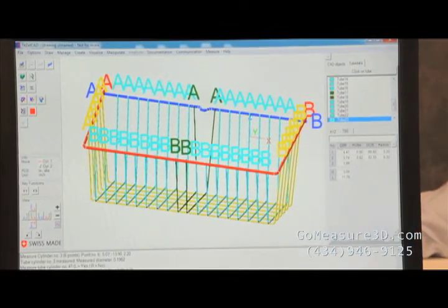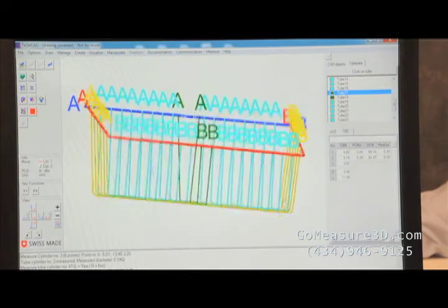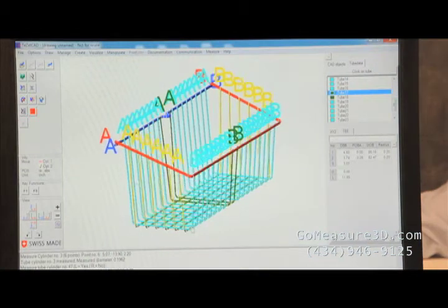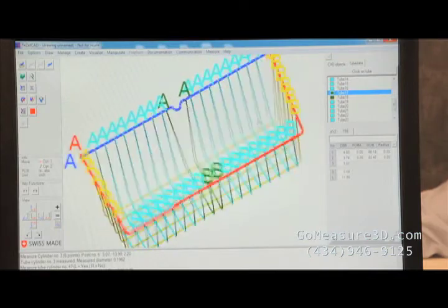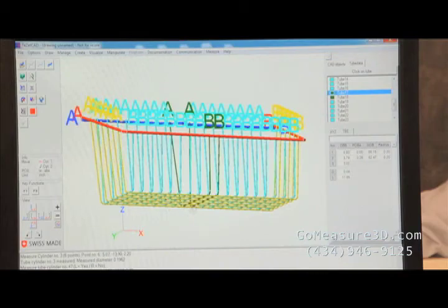Again, tube data, all the data is right here. We could export these, we can modify them, we could move them, we can do anything we want to this data to export it to tube bending. After we bent the first one, we could measure it against a master or measure it against this CAD data and understand the correctable data inside of the bender and then output that correctable data. So let's move on to the export process, and we're going to go ahead and export these and pick them up in SolidWorks.